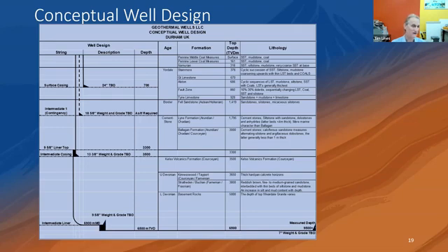And so to avoid having to go down casing sizes and then not achieve 9 5/8 on bottom, we've actually put an extra casing string in here, our intermediate string, an 18 5/8. So we're going to put a 24-inch casing in and then put a 22-inch bit into that, and then drill until, unless we get some kind of failure, in which case we run the casing and carry on in 13 3/8. So that's the kind of thing that you need to think about. You do need very large IDs on bottom, or else it just completely constrains how much water you can flow. So just a thought to you there.